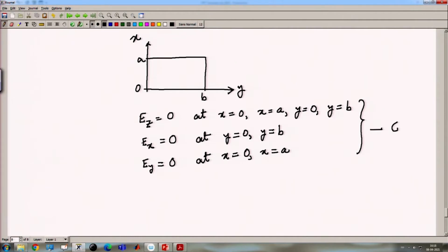So, let us call this equation 6, which defines the boundary conditions that need to be satisfied by the mode functions, the TEx and TMx modes in the rectangular waveguide, or in the homogeneous rectangular waveguide, the rectangular waveguide filled up with a homogeneous material.